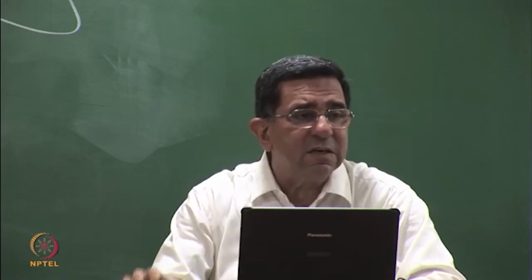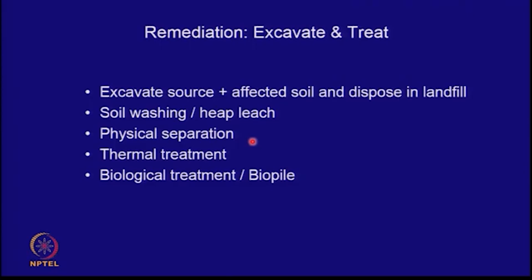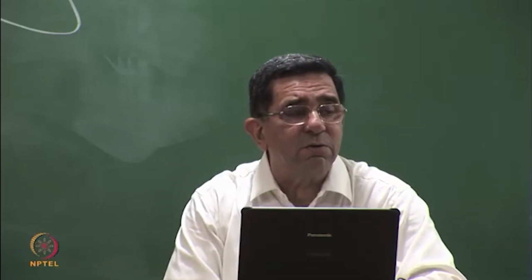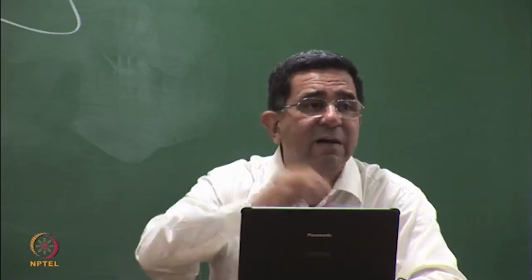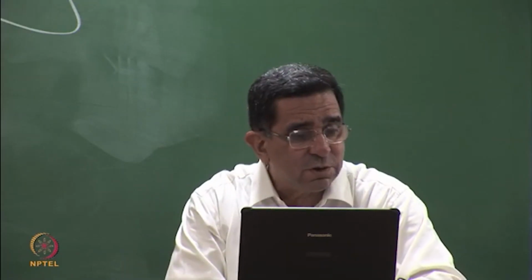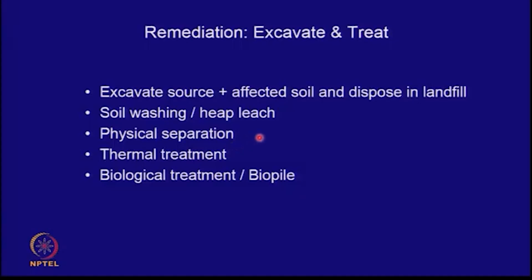So if you can fractionate it, that means if you can do physical separation, maybe you can discard the clay size portion or it becomes much lesser and you can put it in the landfill, and the sand and the silt size portion you can reuse. So physical separation sometimes helps you separate out the contaminated fraction of the soil from the non-contaminated.